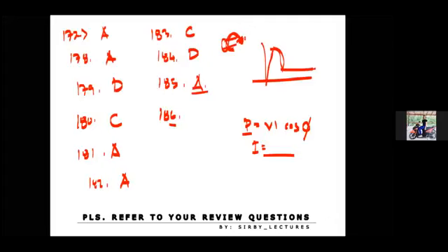Now for letter A, it says that we are to rewind the stator windings, and recall that the stator is a component of an electric motor, inside of which there are a lot of windings. And for letter B, install a forward reverse control circuit, which is also possible. And for letter C, reverse any two connections of the motor leads, and this is what we have talked about. And letter D, install a frequency inverter device.